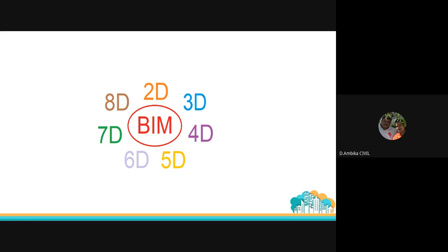So in 4 dimensions, what we do in order to keep up the time or maintain the time is we go for some scheduling approaches like critical path technique or line of balance method, whatever it is. We have different scheduling techniques, and we also have some advanced scheduling techniques like fuzzy logic, heuristic approach, algorithms, simulation, etc. All these scheduling techniques are taken into account in order to maintain the timeline of the project. If the timeline of the project is maintained, then definitely the cost will be reduced. And our motto, being construction people or a construction manager or a civil engineer, is to finish the project in stipulated time and budget. So the 4th dimension is very much needed.